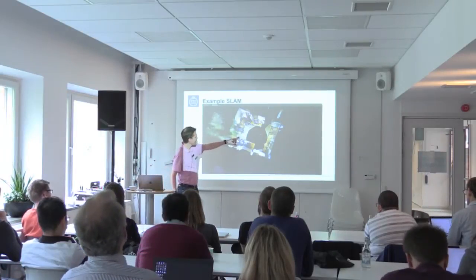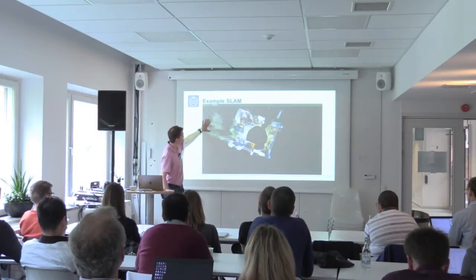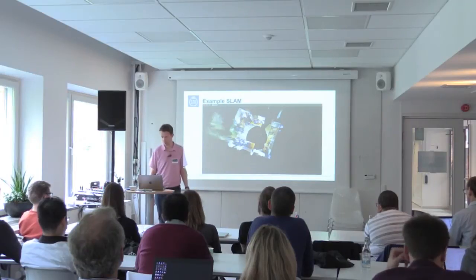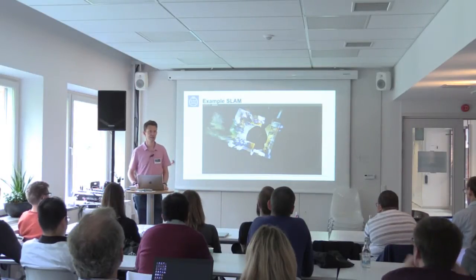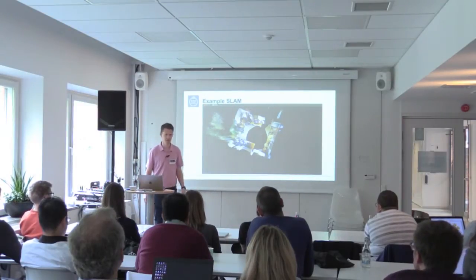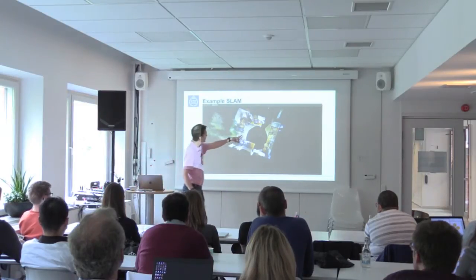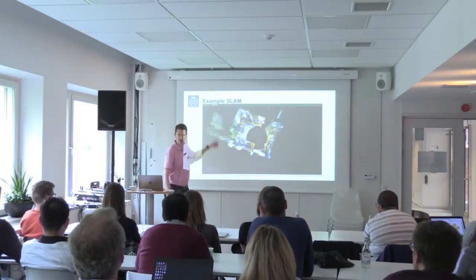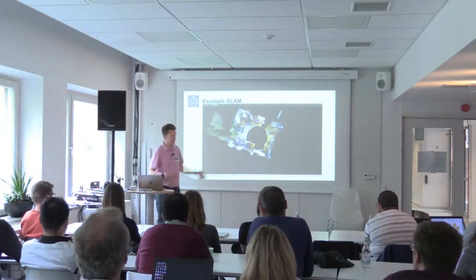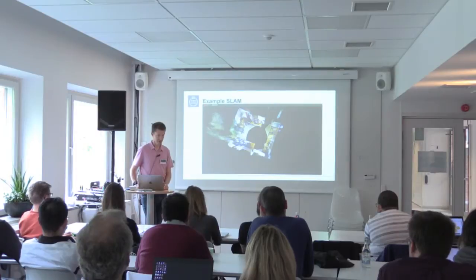You can kind of see from this map here that the depth data you got over here was quite a bit less accurate than the data that was closer to the robot. So why is that? Yeah, it could be a window. In this case, it's not a window here, but that could definitely cause that. Mirrored, maybe. It could be a mirror, yeah. But there is one difference between the points over here and the points over here. The distance, exactly. So the points over here are much further away, and depending on the technology you use, this could have a big influence on how accurate that distance estimate is.